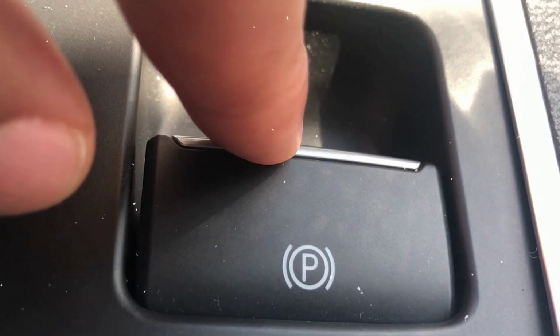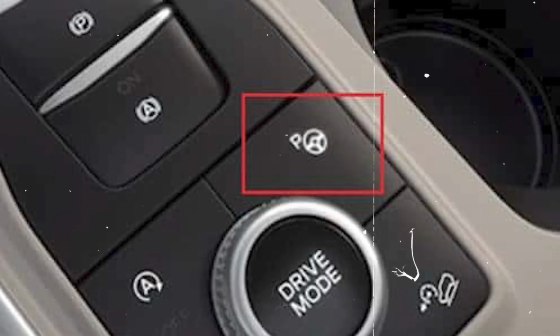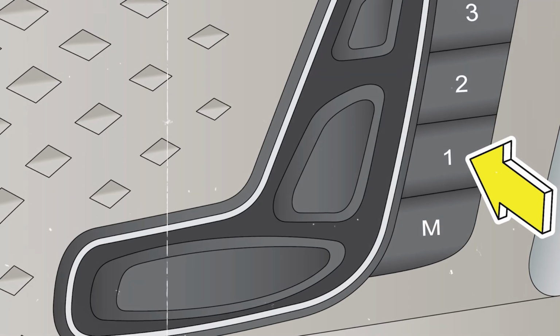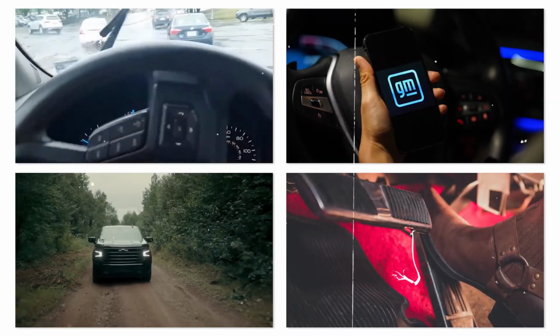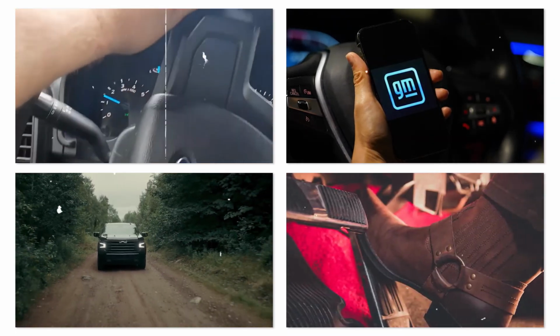Make sure your Ford is parked on level ground with the parking brake engaged. Turn the key to the on position, or if you have push-button start, press the start button twice without touching the brake pedal. You want accessory power on, but don't start the engine. All your dashboard lights should illuminate, and the radio should have power, but the engine stays off.